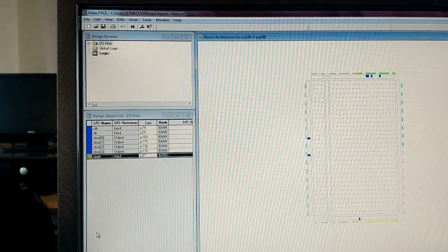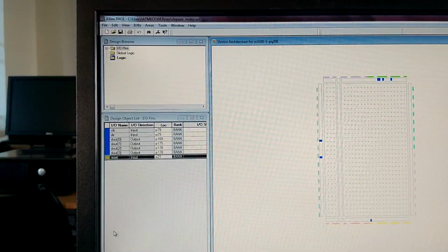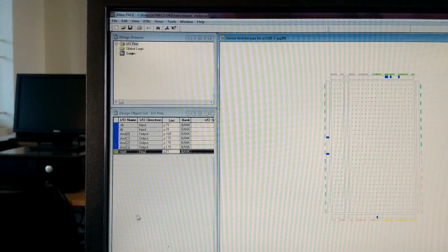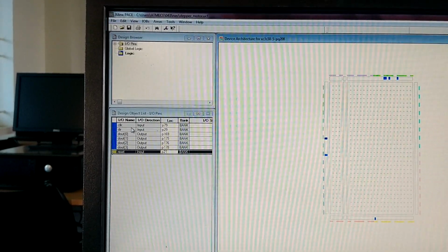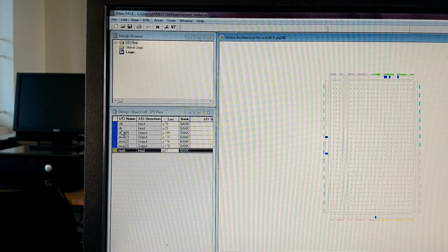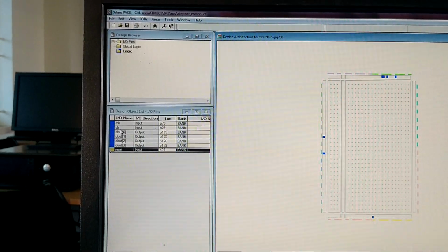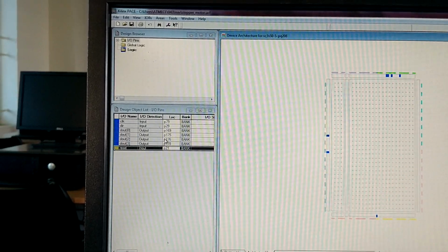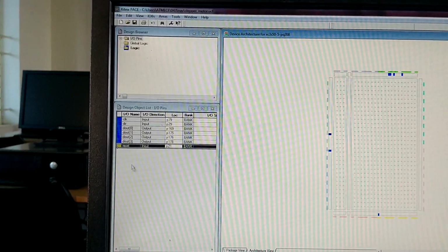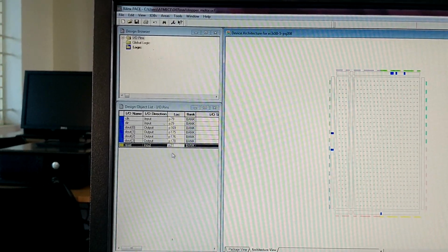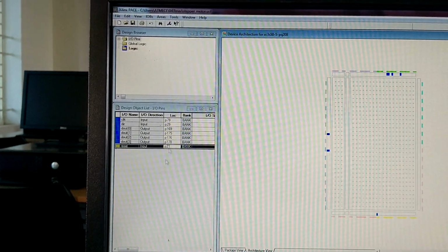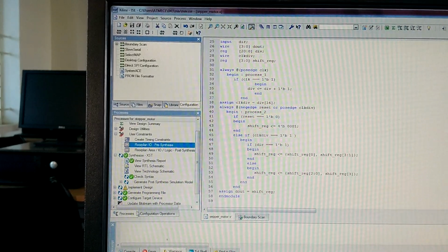So in the FPGA kit we have lot of pins which will be used. So we need to assign the pin which we are using for our stepper motor. So we will be using for clock P79, for direction bit, that is to change the direction, P29, and these are the output pins P169, 175, 176 and 178, and then the reset bit is P21. So you can see here it is marked here. So this is how you need to assign the pin here, and after that we will come here.